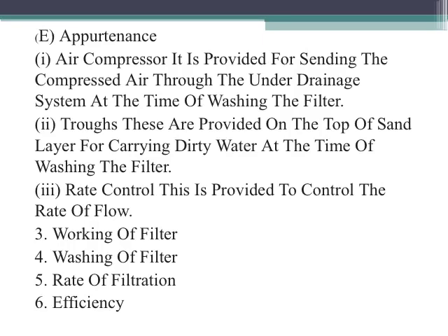We will now understand about the working of the rapid gravity filters. The rate of filtration in case of rapid gravity filter is very high, generally at the rate of 4000 to 6000 liters per hour per square meter of surface area of the filter. Moving on to the efficiency of rapid gravity filters, it is highly efficient in removal of color. It is less efficient in removal of bacteria. It can remove turbidity of up to 30 to 45 NTU.